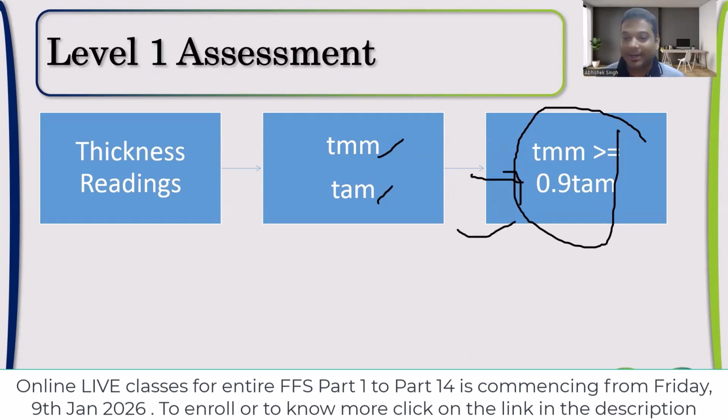Let me ask another question, which may give a hint. If my starting thickness was 20 mm, and I measured an average thickness of 19 mm, but at one or two places, or very few points that were close together, the thickness was 15 mm, what does it indicate? Localized wall loss. Do we actually need an assessment or not? Correct, localized nature. By using this criterion, we are deciding whether analyzing by Part 4 is a good idea or not.